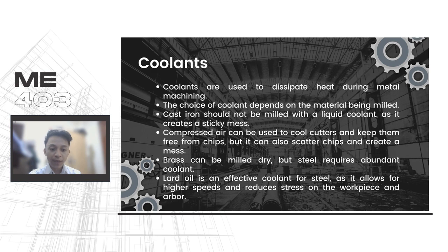Different fluids and compressed air serve to dissipate heat during metal machining, with the choice of coolant contingent on the material being worked. Cast iron, milled at typical speeds and feeds, doesn't overheat milling cutters and should not be used with a liquid coolant, as it creates a sticky mass when mixed with cast iron chips.